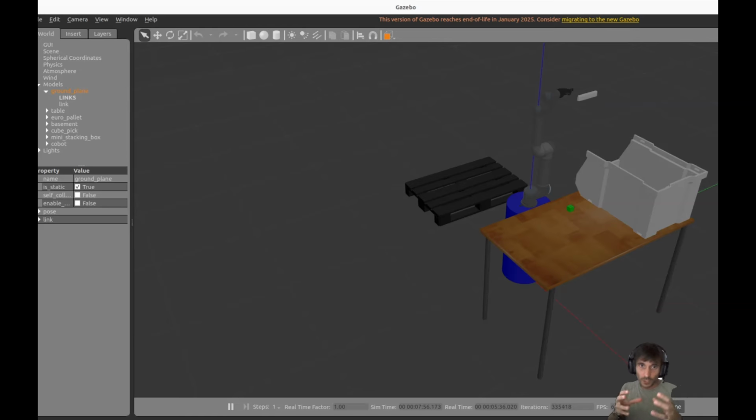What I'm going to do is start and show you how MoveIt integrates sensor data from the camera that we have simulated in our environment, which publishes a topic of type point cloud, and MoveIt is able to integrate this data in an Octomap from this 3D camera so that the robot can adapt to dynamic obstacles in real time. Then we will see the advantages and drawbacks, and we will start by looking into how